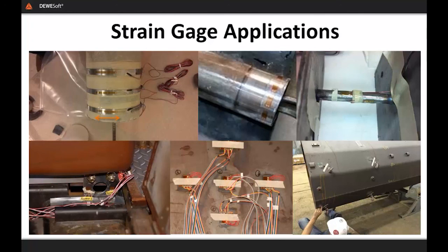The shafts that you see in the upper left and center are examples of measuring strain gradients on very different materials. Again, note the significant difference in gauge length between the two examples. In the lower left are Rosette gauges on a roller coaster used for dynamic analysis of a bracket with previously observed failures. It's nice to know that they were looking into the cause, hopefully with the intention of preventing any accidents. The lower center is actually a homemade transducer. It was used to determine damping coefficients of various materials for dropping large weights in a workout area. I wonder if the large weights were the people who possibly needed to be in the workout area.